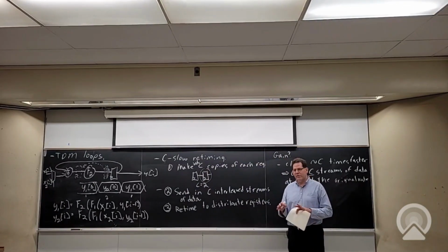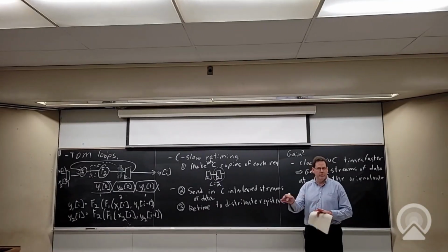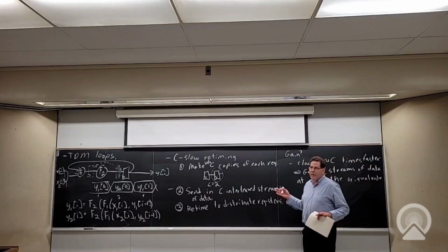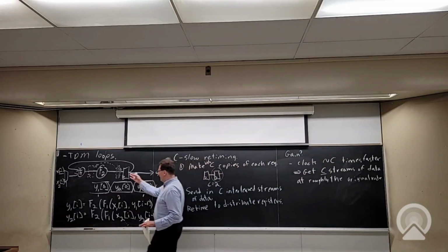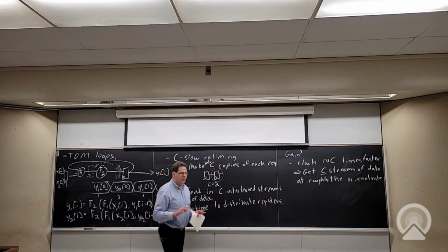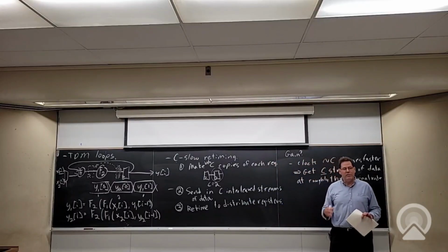Synthesis is just taking your HDL, turning it into basic gates, then optimizing the gates, then it tries moving around the registers. The advantage of doing it in synthesis is that not much has happened yet, so it can move around registers basically the way I am. Like it can say, I take this register and I move it there, and I just change it in the netlist, and I do some checks to make sure it was legal, and I'm done. So it's relatively fast, it's not very disruptive.